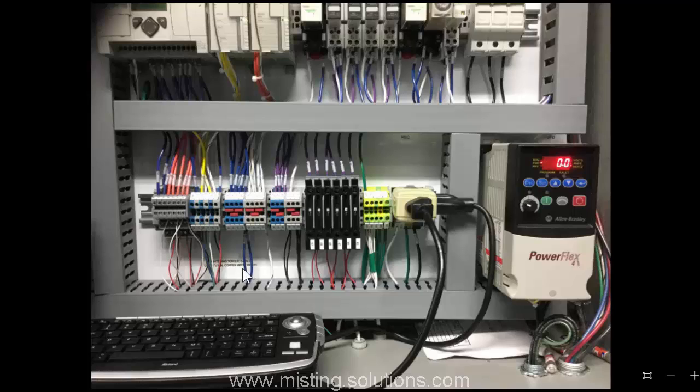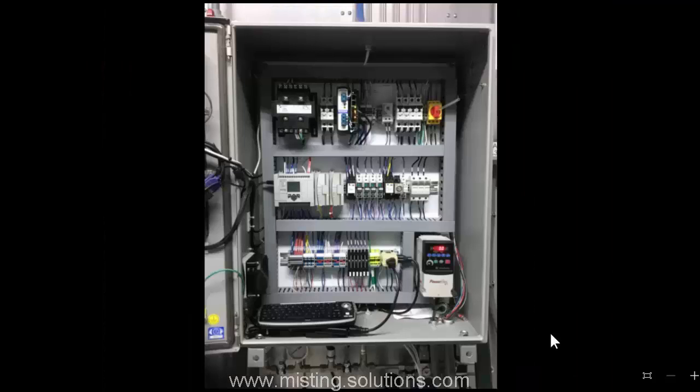Now, the building automation system that we just talked about, the Johnson Controls wires, land right here in this section. And if we look at the control panel as a whole, they're right down here in the terminal strip section. So there are three sets of wires here: the 0 to 10 volts DC, and that signal is going to go into the microcontroller section, into this first I/O module of the microcontroller. The run signal, or actually we should say the enable signal, goes to the microcontroller also, but it goes up into this input section up here.